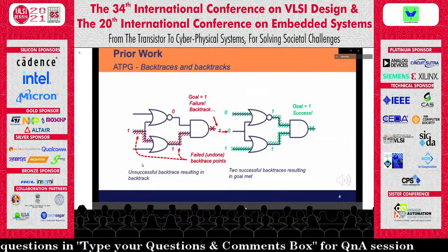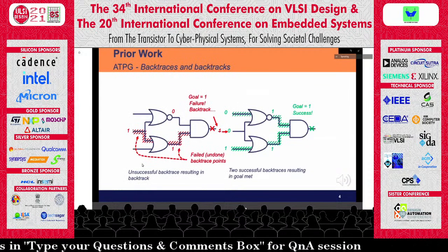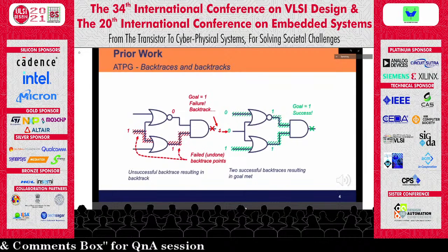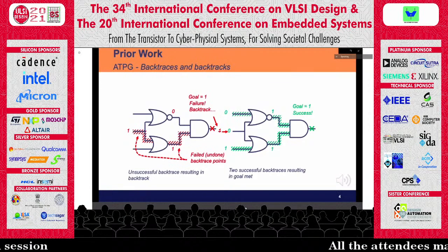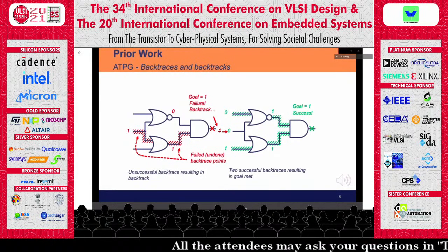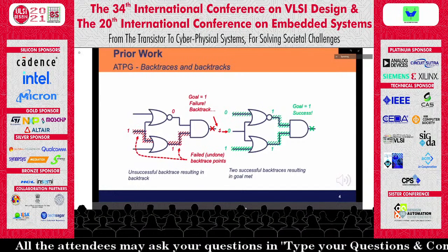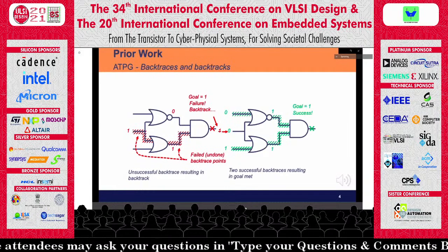To avoid this upper limit, most ATPG algorithms employ backtracing subroutines. These subroutines trace backwards through a circuit starting from an objective, such as exciting or propagating a fault, and attempt to find input assignments which accomplish the objective. Multiple backtraces from an objective may be required to meet the objective. But if these input assignments accomplish the final goal, that is, find a test for the fault, then at most I input vectors must be simulated, which is nothing compared to the theoretical maximum of 2^I.